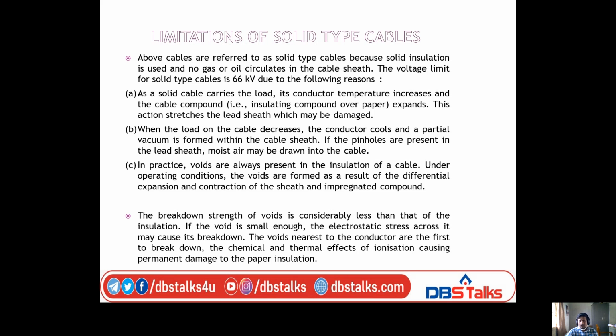In practice, voids are always present in the insulation of a cable under operating conditions. These voids are formed as a result of differential expansion and contraction of the sheath and impregnated compound. The breakdown strength of a void is considerably less than that of insulation. If the void is small enough, the electrostatic stresses across it may cause its breakdown.